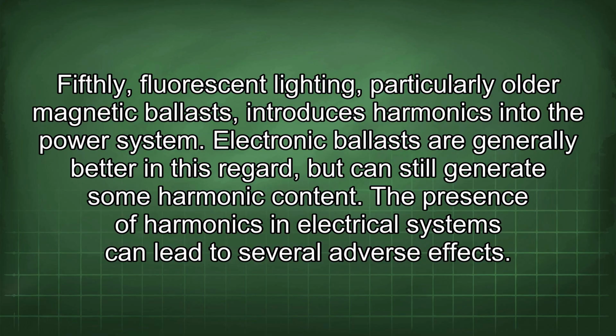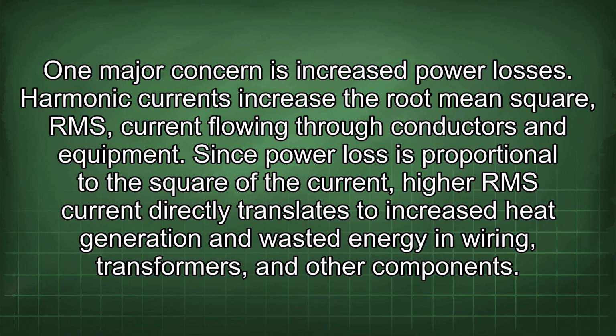The presence of harmonics in electrical systems can lead to several adverse effects. One major concern is increased power losses. Harmonic currents increase the root mean square, RMS, current flowing through conductors and equipment. Since power loss is proportional to the square of the current, higher RMS current directly translates to increased heat generation and wasted energy in wiring, transformers, and other components.